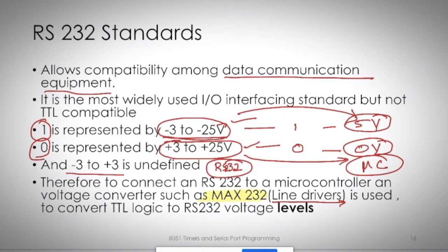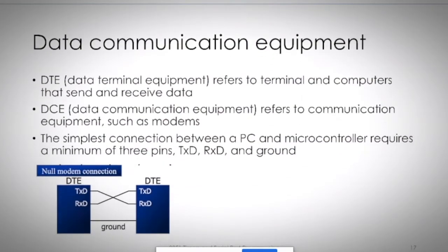These are the main things you must remember. RS232 is not TTL compatible. Here the 1 and 0 are represented by totally different voltage levels, which are incompatible with TTL logics, and we will be using a line driver to make the compatibility possible. So this is about the basics of the RS232 standard.